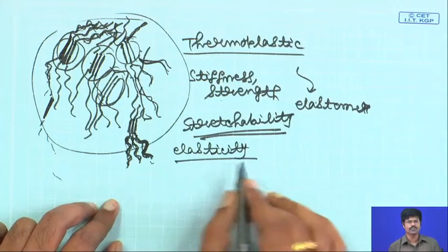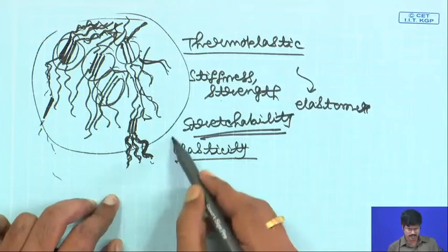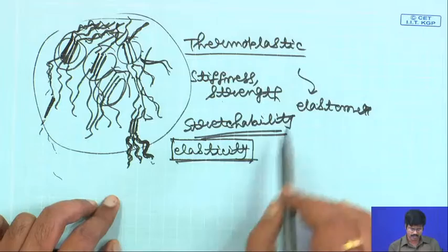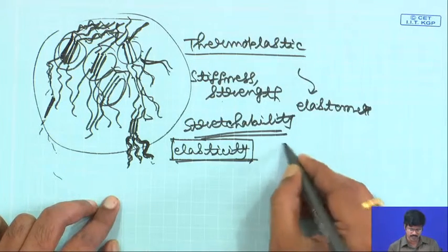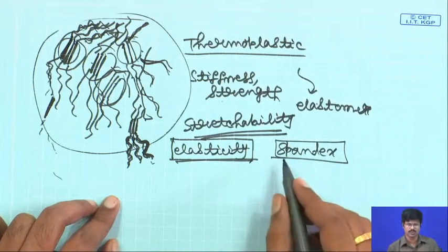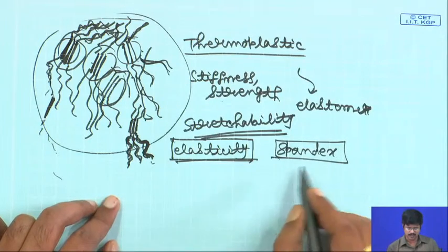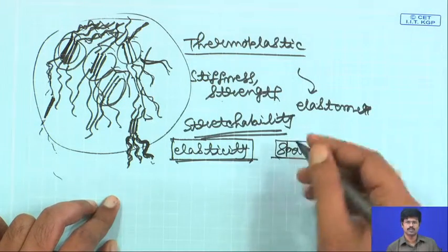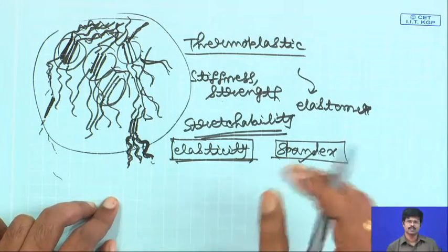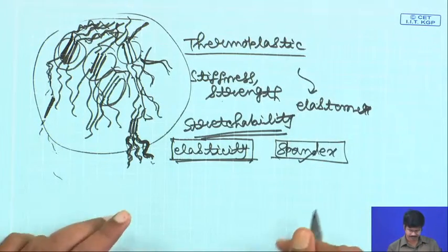It will be non-linear of course, because your stress versus strain is not linear after that, but it will still be elastic. That is why it is called thermoplastic elastomeric material, and as I have already told before, spandex has use in your fabric, in your clothes, especially for soft sportswear. You will co-spin this particular fiber with your nylons or with your polyesters. So, this also will go into the fabric, that will give the stretchable property to the material, that can withstand a lot more wear and tear.